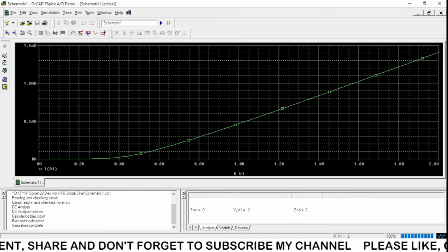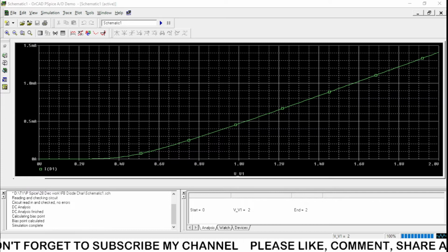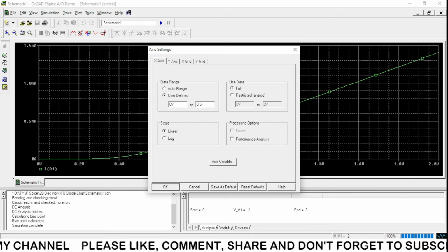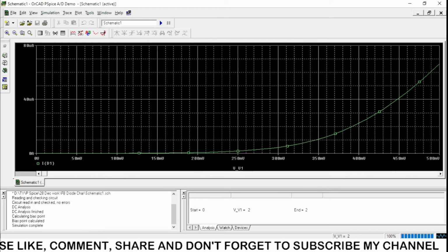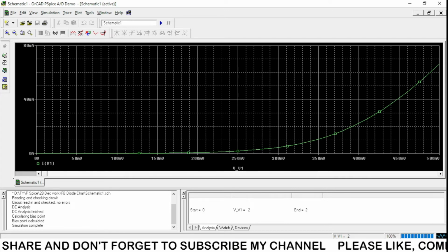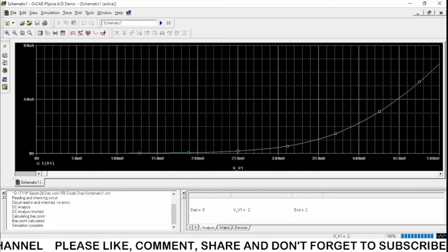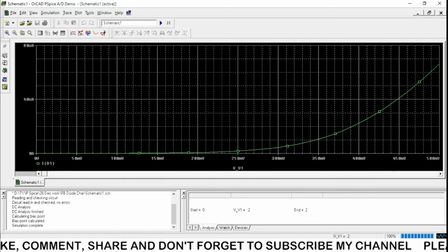Now you are seeing the graph. The graph starts from 0 volt and ends toward 2 volt. So if we double click over here, we can limit the range, say to 0.5 volt. I'm saying okay. You can look at here up to 500 millivolt. The graph is shown in here, and from around 200 millivolt onwards, the graph slightly goes in the positive direction, and you are seeing the scale over here. It is 40 microampere, 80 microampere, and so on.